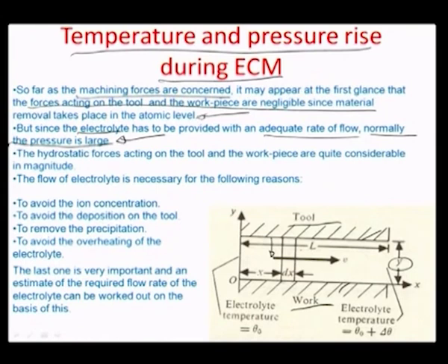So, you should just operate below the boiling point, and the heat that is being dissipated by the current density because of ion transport of the fluid flow should be just enough to make the operating temperature of the electrolyte below the boiling point, and therefore the flow of this electrolyte is definitely necessary for that.